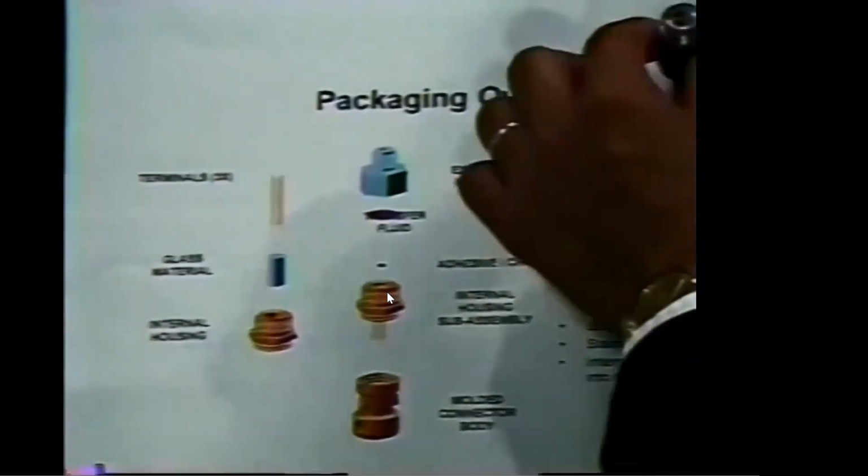Let me talk a little bit about the packaging that we do on the die now. The packaging that leads to a device like this involves several different back-end processes. We start out with a die that I just described to you. We adhesively mount that to a glass in a glass to metal sealed package that we buy externally.